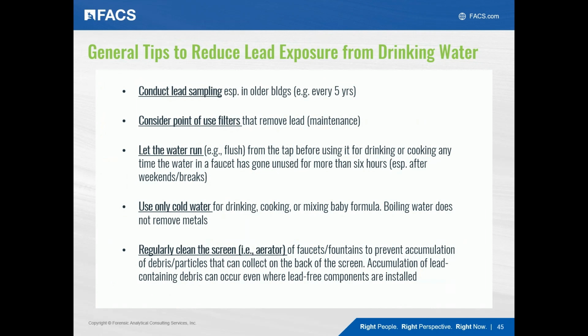and any of these factors can change. So we actually saw this in Flint, Michigan. When the city changed the source of the water, it wasn't that the source water contained more lead. It was just that the water that they changed to was more acidic. And that resulted in more lead leaching from the city's lead pipes.